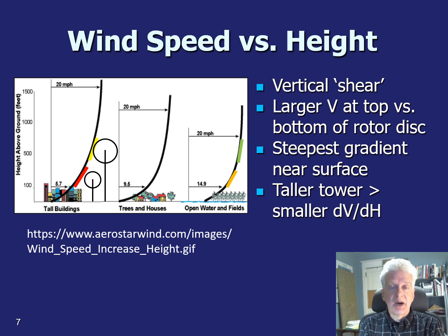That means that each blade, as it passes the top of the tower, encounters much higher wind speed than those passing across the bottom, and that creates stresses and torque inconsistencies in the rotation. That's a factor in the productivity of the wind turbine. So building a taller tower can get you into both higher winds and winds with less shear.